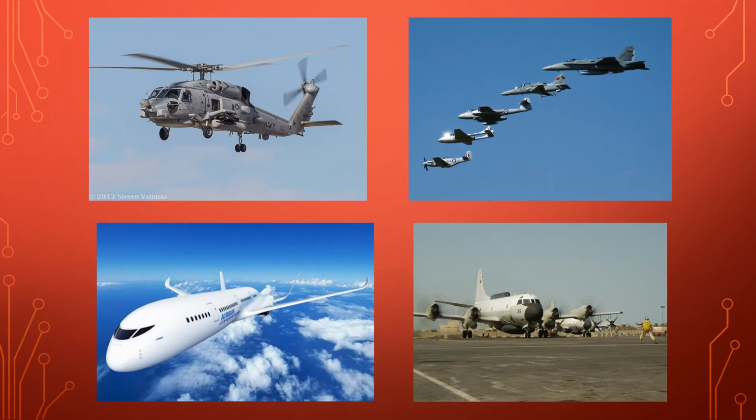Following engine startup and acquiring adequate RPM, the APU can remain running, though it is typically shut down because at this point engines can sustain the power necessary to maintain electricity throughout the aircraft, utilizing the sequence discussed in prior slides. Should AC power be lost in flight, secondary and tertiary backup systems can be resourced to restore power to critical systems.